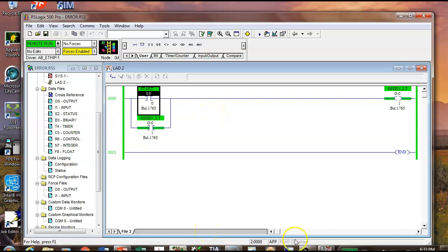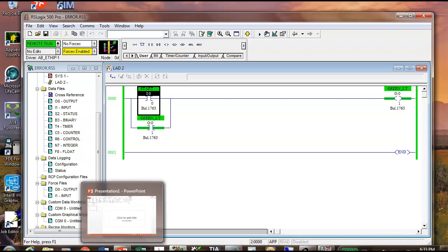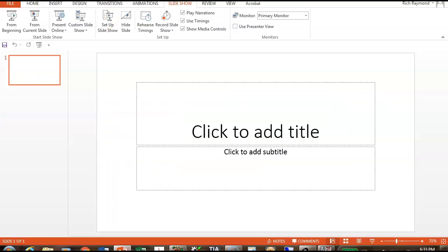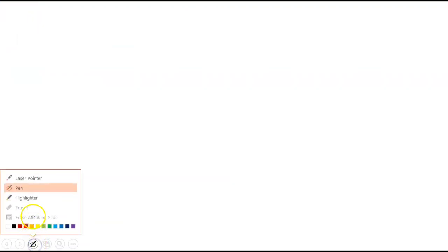So if I was going to draw this in PLCs, and this is a very important concept to understand, guys. In motor controls, if I was going to draw this circuit right here, this is a standard start-stop station. We call this thing a start-stop station. We call it a memory. We call it a seal-in, and it's also called a three-wire control.